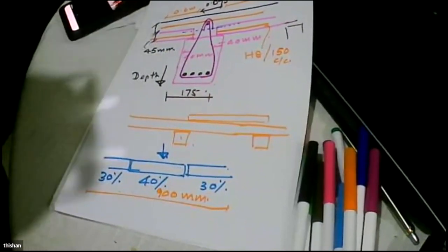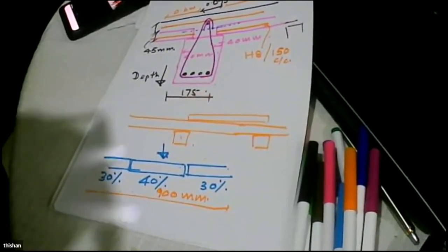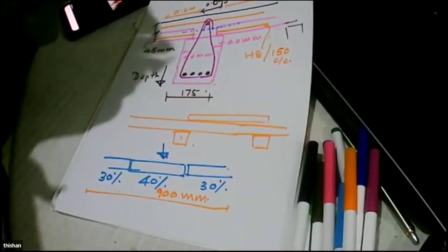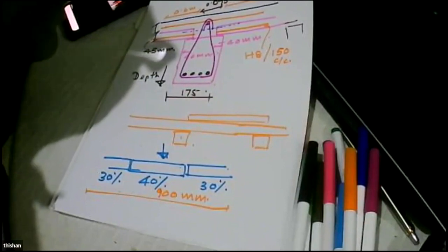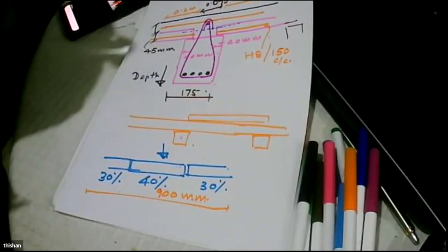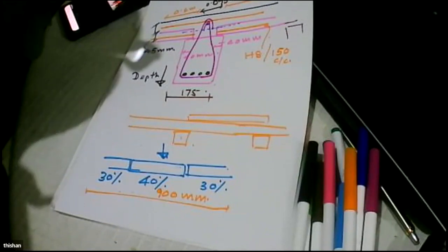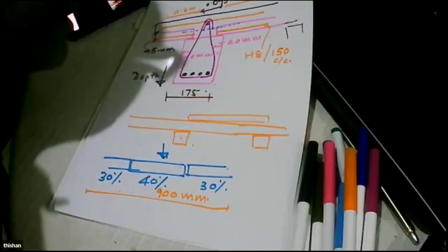Then can we use precast slab and beam for washrooms and roof slabs? Precast slab is very good because on top of that we have a screed, high quality screed, not just normal concrete. And because of the design features, you can easily have a washroom up to a width of 2 meters with precast slabs.